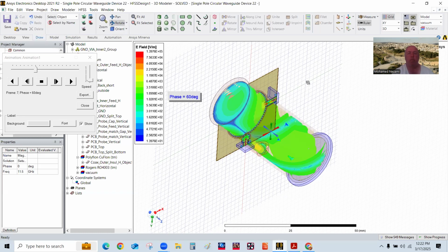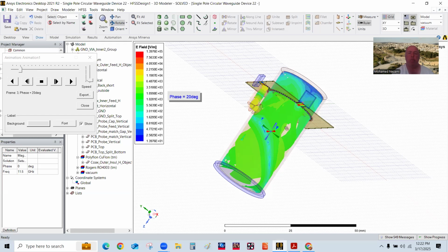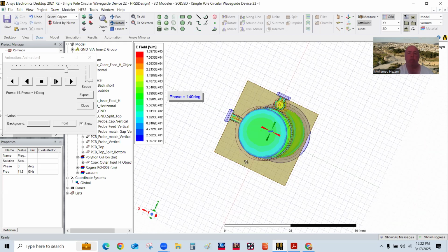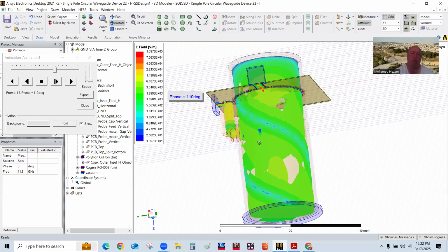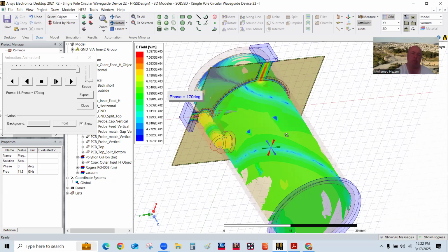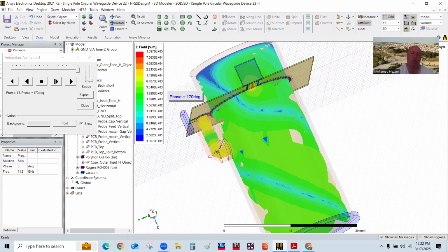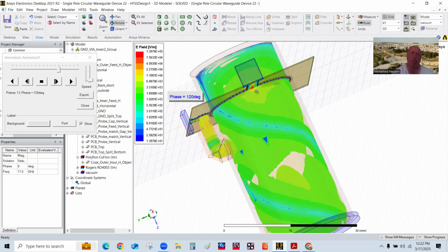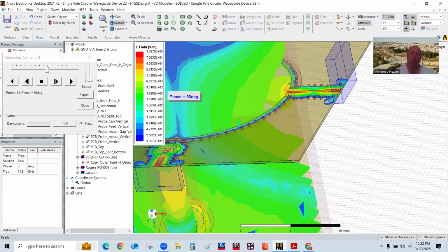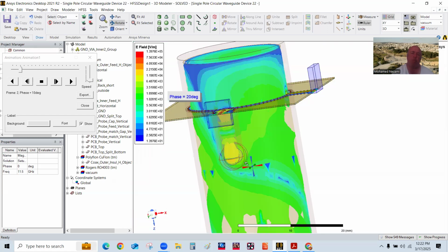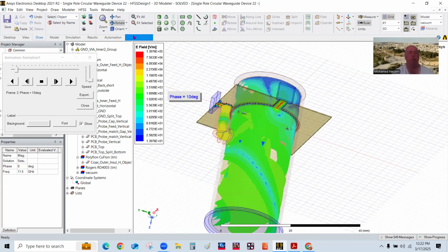Okay, so you can see now what I'm doing is I'm propagating a signal from this end, and this is rotating counterclockwise. So I'm going in, and you can see that one polarization is getting picked up by this guy in here. And the other one is going through to the other pole, the printed pole. So we've got the printed pole and the metallic post pole. Okay, and it's working nicely.